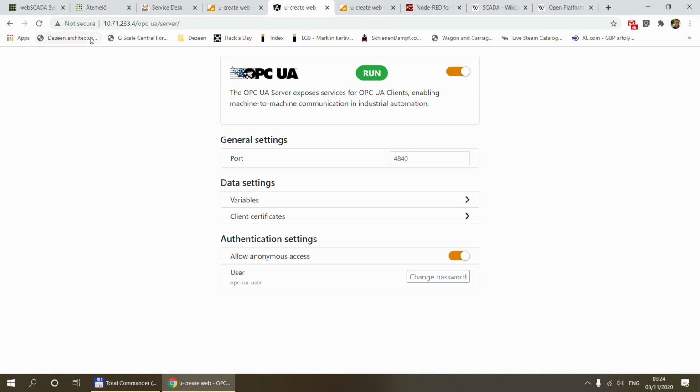In my case, the Weidmüller Automation Controller is running in the same network as the SCADA visualization client. So there is no need to set up any additional data security, but as you can see, there are various options available if you need to do that. If the automation controller is connected to the OPC client via the open internet, you probably want to set up some sort of security. So you have a couple of different layers of security.